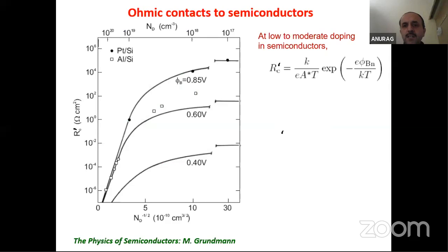And you can see what are the important things. Whenever you are depositing a metal, for fabrication of a metal semiconductor contact, you are depositing a metal over a semiconductor, and now you do the IV measurements. So what we calculate of this contact, there is a barrier which is formed, and this barrier is quantified by barrier height, what we call the phi_BN, the Schottky barrier height. In this graph, which I have taken from Marius Grundmann's book,